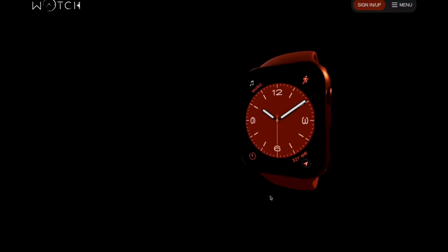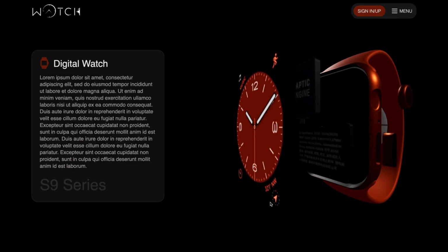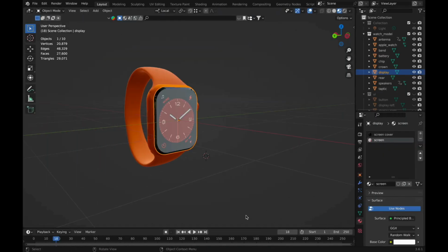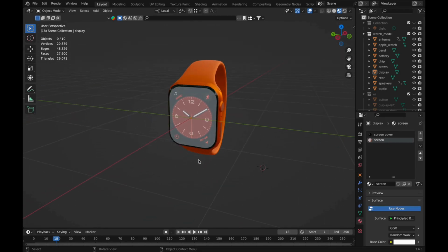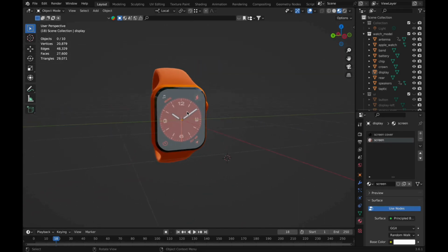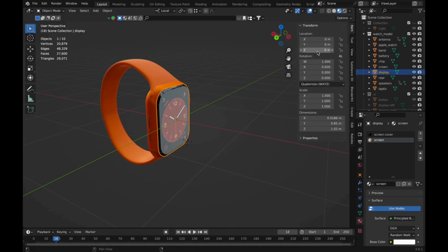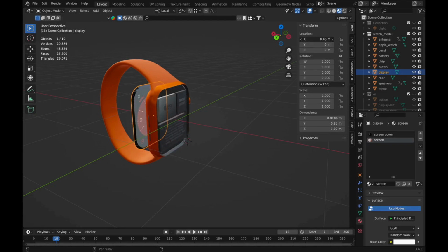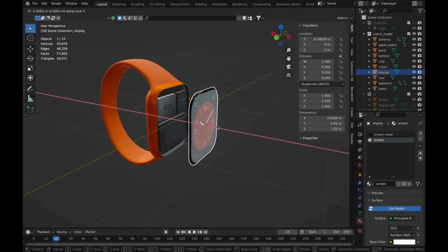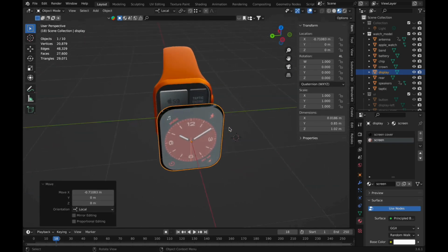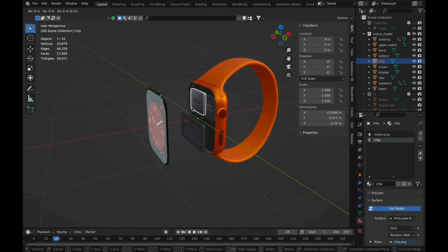The next step is to implement animations for the internal elements. For a moment, I go back to Blender to better understand the task. As you might remember, this is exactly the screen where I split the model into multiple meshes. If I select any mesh, I can change its position in space using the transform tools or by using keyboard shortcuts. I define positions for the elements that represent a keyframe where they are maximally offset from their base position.